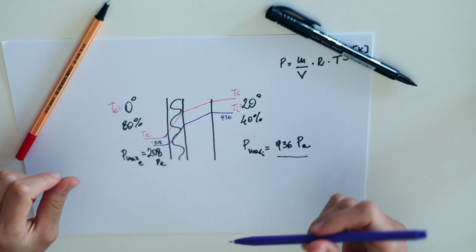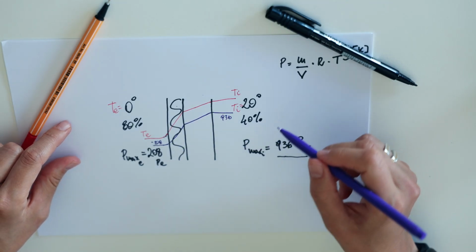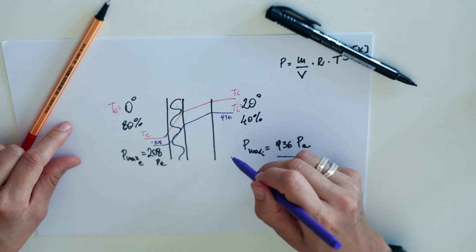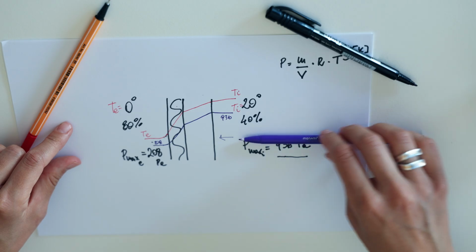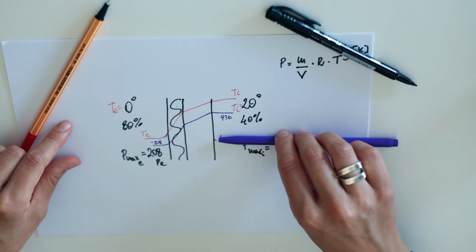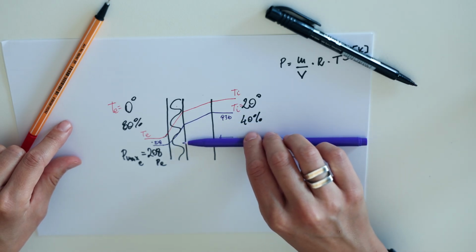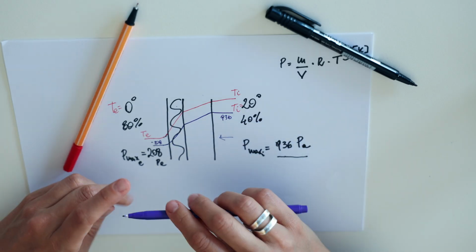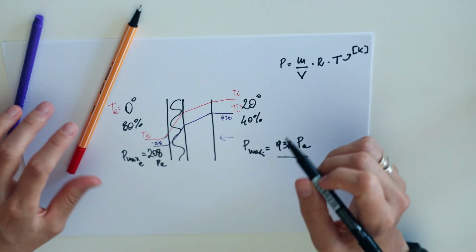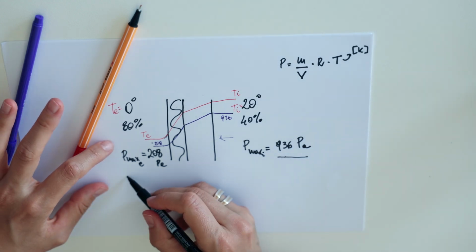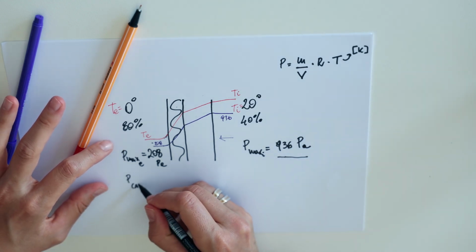But of course, the air with moisture, because it's warmer inside than outside, will travel in this direction usually. So what we need to see is whether, while the air is traveling across the facade, it is at any point condensating. So if I was to draw now what is the missing link, it is the so-called calculated pressure.